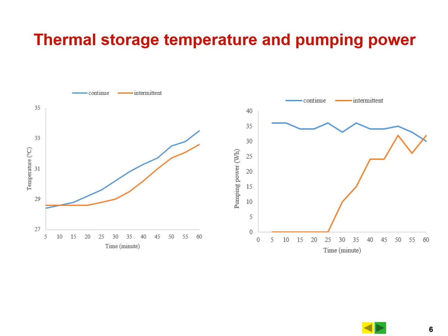The setting of the water temperature cycle for intermittent flow mode highly affects the total energy consumption. For continuous flow mode, the energy consumption is about 393 watt hours, and for intermittent flow mode it is about 165 watt hours. We can calculate the energy saving at about 58%.